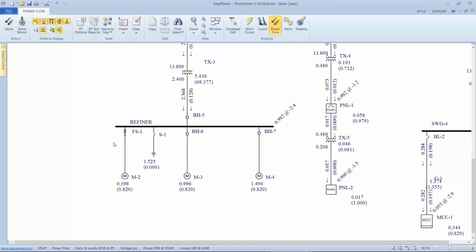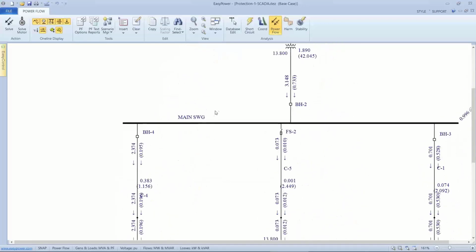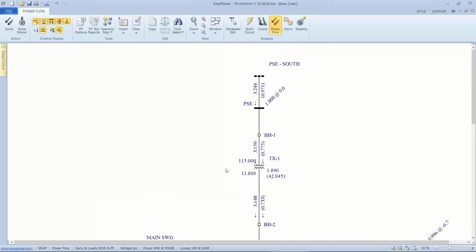So we put in 1.55, and we're getting 1.52. Part of that is because we have a higher voltage, but we've reduced the flow through the circuit by over a megavar, which is impressive. So our losses will be diminished quite a bit. But what's more impressive is that by putting that power factor correction in, we bring our power factor up to a sterling 0.97, which puts us well within the limits for working with the utility company.